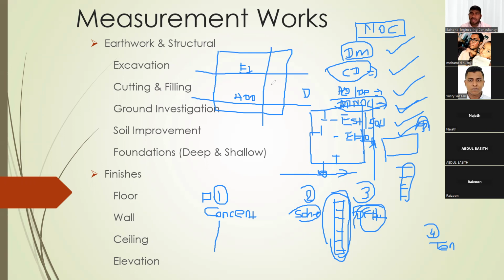So you have to get a no objection certificate from all these authorities saying that this plot doesn't have any existing live utility services. Then you can go ahead with the excavation, because here most buildings have a basement. You will go for 5 basements, 4 basements, whatever it is. Then you have to go to a depth of 30 meters or 16 meters or 20 meters. Normally utility services are within 2, maximum 3 meters. So when you're doing excavation, if you cut a fiber optic cable serving Etisalat, then the entire Abu Dhabi will be without internet. So you have to be careful.